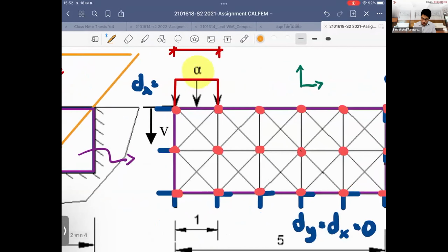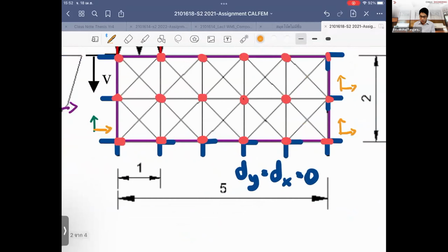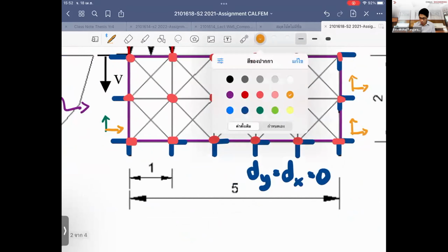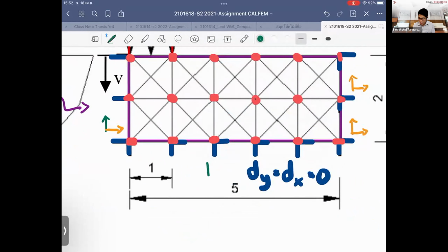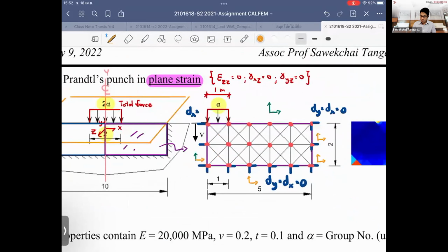So in this one here, we have the nodes that are free in the vertical, but in the horizontal direction, it has been frozen. So you have different types of degrees of freedom, right? The one that I draw in the yellow, or brown color, I indicate that this is the restrained degree of freedom. So it doesn't have movement. So it's at the support, right?